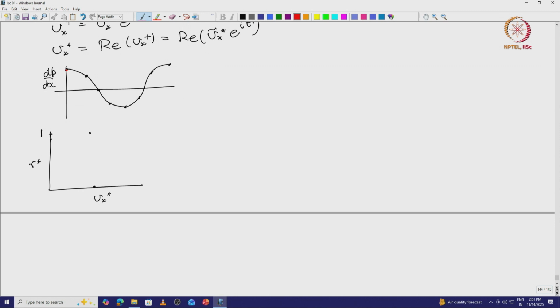If I take a small value of Re omega, 0.1 say, then at this point you get something that looks close to a parabolic velocity profile. If you go to this point, it is positive and you get something that looks like this, nearly a parabolic velocity profile, when this parameter Re omega is small. And then at this point here, you get something that is almost flat.